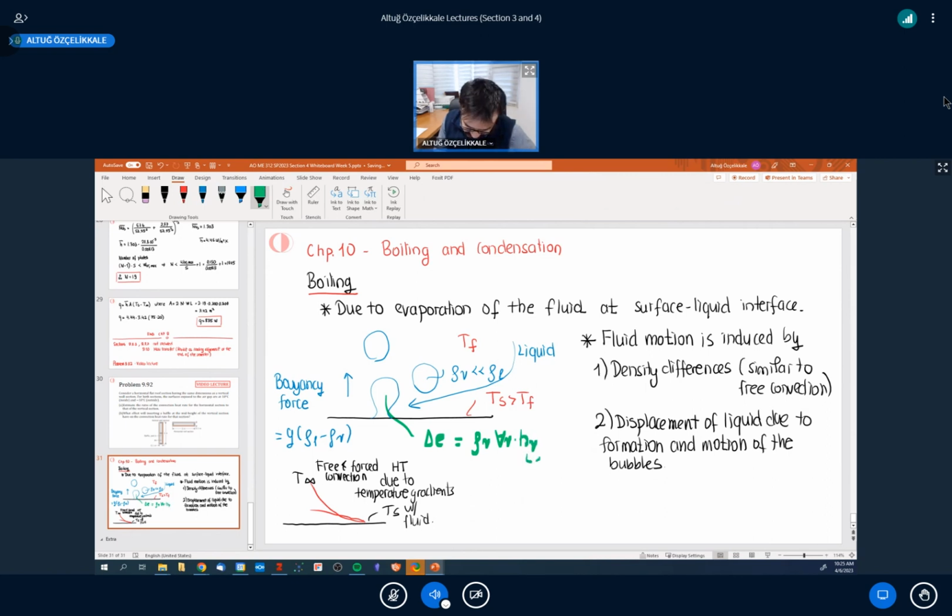That's my enthalpy now, let's not confuse it with convection heat transfer coefficient, minus density of the liquid, volume of the liquid multiplied by enthalpy of the liquid, right? But in essence, when you write it this way, you might be asking, why are you not writing this as some mass multiplied by the latent heat of vaporization, h_fg? So now this is essentially the main player. There is very high energy density due to latent heat associated with the phase change.